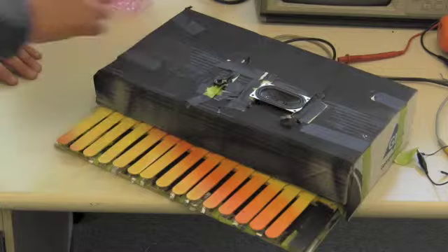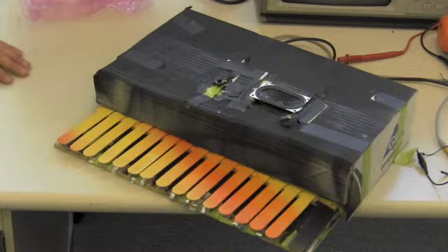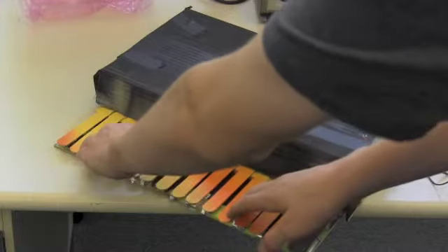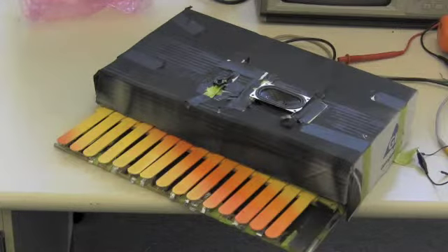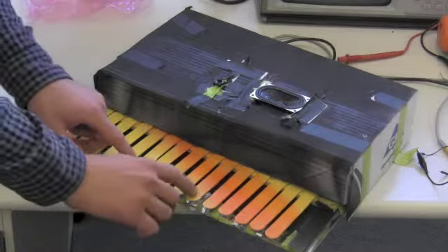Yeah. And then if you wanted to, as I said before when I was talking about combining the buttons, we have the code there. It just sounds really weird. So that's because of the way square waves add together. When you add 2 waves, a lot of the time you'll have a wave that, all right, I'll draw it up on the board when we're done with this. But basically, when the waves add together as a square wave, you end up chopping between the 2, as opposed to when you add as a sine wave, because it's a more continuous wave as opposed to just on or off. They come out really nice when you add them as sine waves. Some sound kind of cooler than others, though.